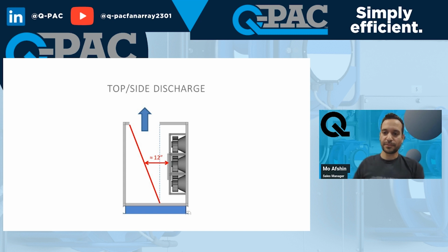Quick interruption: downstream clearance for coil versus filters, is it the same? Yes, that would be pretty similar. Again, when you're designing a blow-through system, you're not going to get as good of a flow distribution on your component, either coil or filter. So it's always recommended to use a draw-through system. I know that's not always going to be the case. There are times that you have to go with a blow-through, but yeah, that would be the same. Again, designing the speed, the face velocity on your component, is very important. So make sure that you're designing it with the right number.